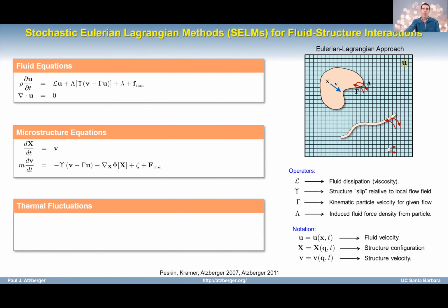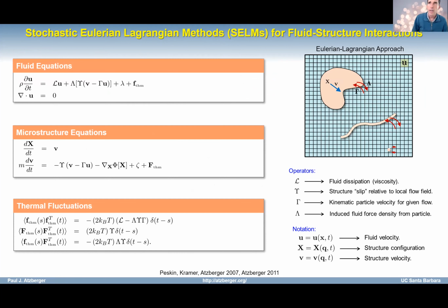This is really, like I said, in the spirit of things like immersed boundary approaches. And the idea is you have two overarching sets of degrees of freedom. You have Lagrangian degrees of freedom that can live anywhere in space, and the Eulerian degrees of freedom, which typically will be discretized and fixed in the lab frame. So you can have point particles, you could have filaments, you could even have fully volume-encompassing elastic bodies. It really doesn't matter which case you're in. It'll all boil down to an appropriate choice of coupling operators: one that tells you the kinematic response of the Lagrangian degrees of freedom to the material state, and another which tells you, for a force or a stress that's applied, how that acts on the momentum field of the Eulerian degrees of freedom.